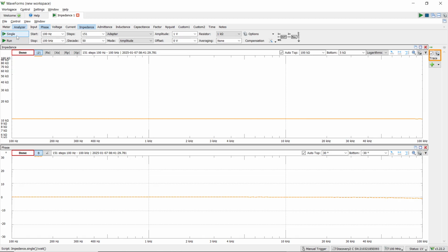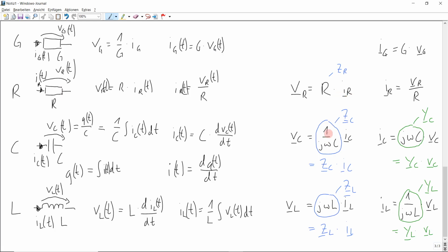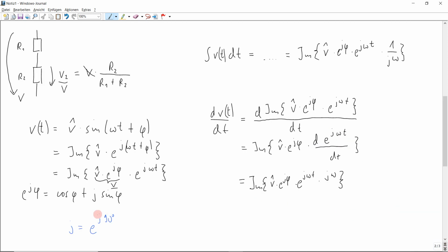A slope, and a slope like going up or going down. It should go down with frequency because this is what we discussed here. Impedance should go down with frequency and the phase should be, the phase is 1 over J, and J was 90 degree, 1 over J, that's why it should be 1 over e to j 90 degree.